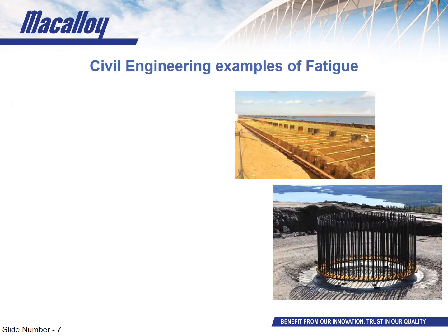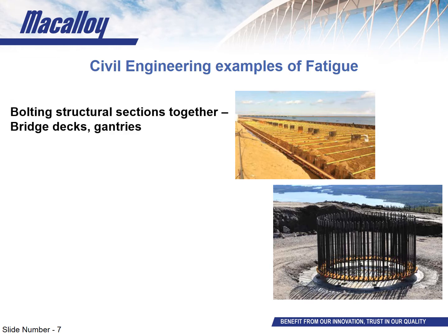By no means is this an exhaustive list, but these are a few examples of applications that can experience fatigue. Now this is to give you an idea of the application so you can relate to it when we're discussing more detailed points later on. Structural sections that are bolted together using steel bars such as bridge decks or maybe gantries can be subjected to oscillating loads as the structure is loaded and the sections move relative to one another.